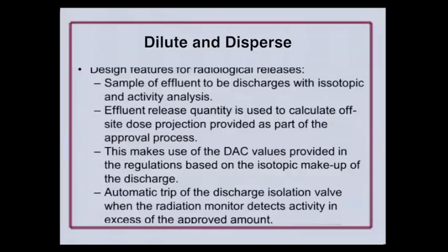Any questions on dilute and disperse? Usually get eyebrows raised. I saw Jerry's eyebrows raised and he grinned a little bit. Because there's a little saying in RP land, it's called dilution is the solution. But it is an approved and perfectly legitimate way of disposing of rad waste. It's a design method, as long as you follow all these and use it as an approved release. This would be called a monitored pathway, and it would be a monitored release. Any questions?